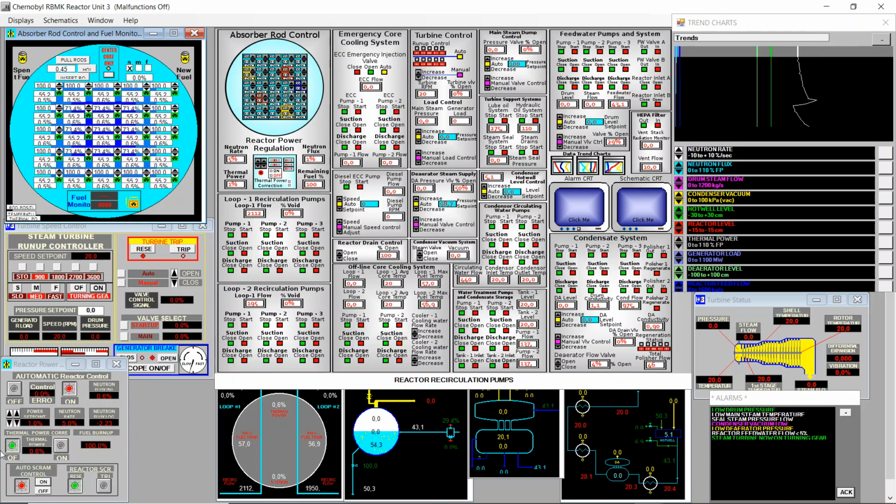So we're at 1% neutron flags. I will increase to 1.5 here, and now I will pull rods. I will hold immediately after, because otherwise it goes too high, the neutron rate. And now it's already controlled. I would say it's already in automatic control. I will increase here the power set point to see. Yes, now it went down because it was just a bit above the 2%.